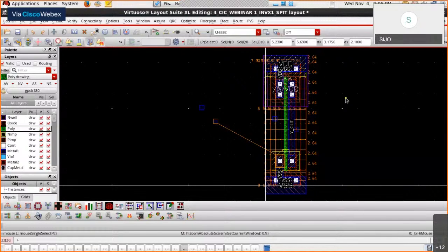It is actually GPDK, and I don't know whether we have the right information. But if you look at some real foundries like UMC or TSMC, they will give you the layer map information. There is a pictorial representation, from the substrate to your top metal, of the various layers available and the dielectrics in between.